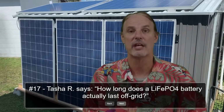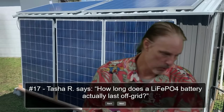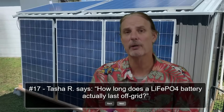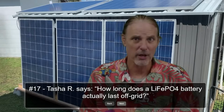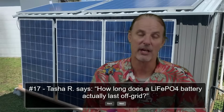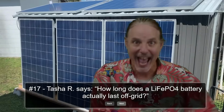And I would suggest that you go in once a year and run that capacity test. You run that battery all the way down to 0 and you charge it back up. And when it truly gets to 100%, you determine what that state of charge is. If it's a 300 amp hour battery and you only get 287 amp hours in there, set the battery size to 287 amp hours so that your state of charge can be accurate.